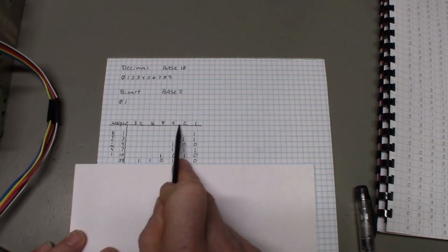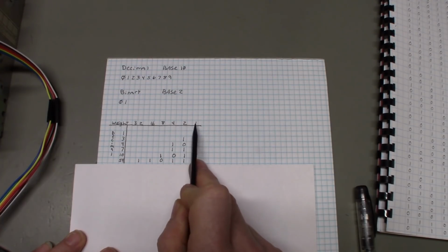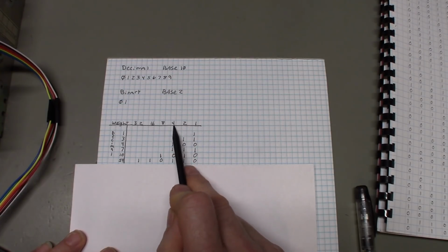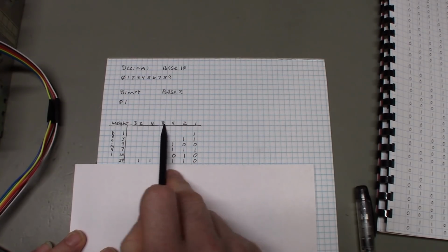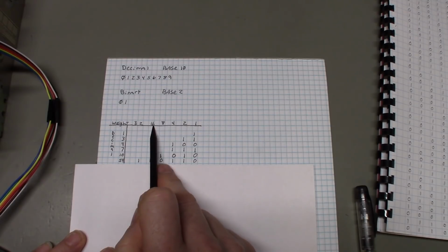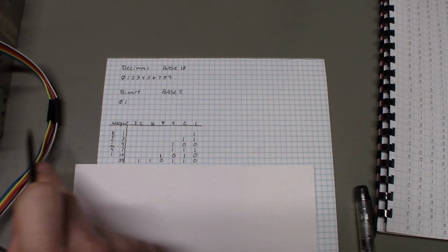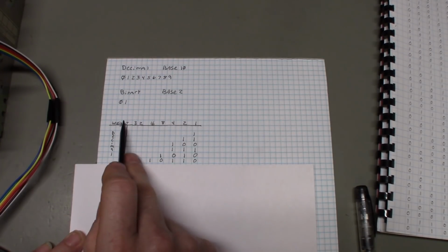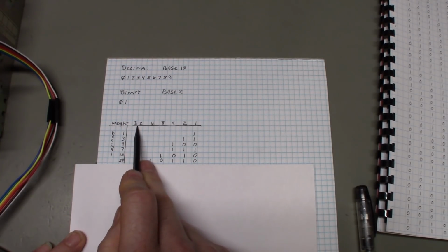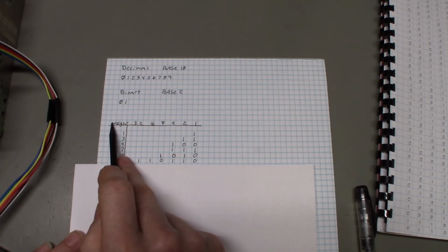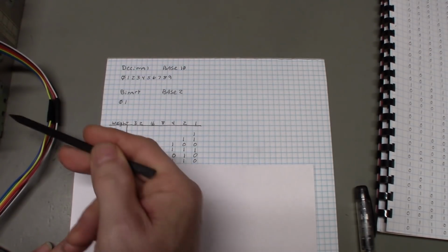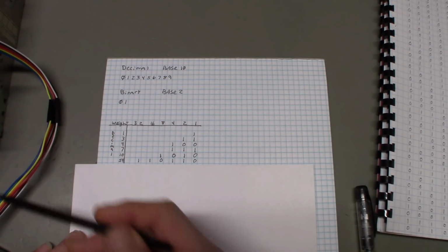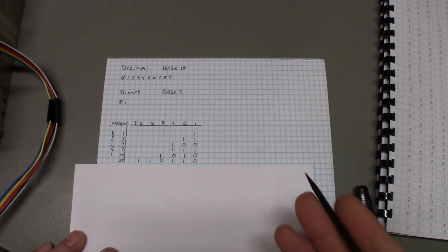And if you notice, the weights I have written up here are multiples of 2. So 1 times 2 is 2, 2 times 2 is 4, 4 times 2 is 8, 8 times 2 is 16, 16 times 2 is 32, and it would just continue on like that. The next column, if we had to make an even bigger number, would be 64, because 2 times 32 is 64, times 2 is 128. And for this radio, the highest or most significant digit used with this PLL is 256, which is 128 times 2.